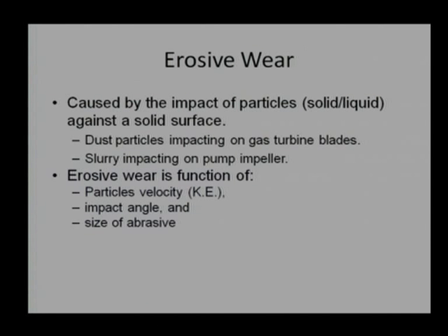This is the last lecture slide, erosive wear. We said that impact energy, or kinetic energy, is required to initiate erosive wear. Particles, either solid or liquid, should come with some velocity, impinge on the solid surface and impart some kinetic energy to it. As this is a momentum transfer, the angle of impact will be an important parameter.